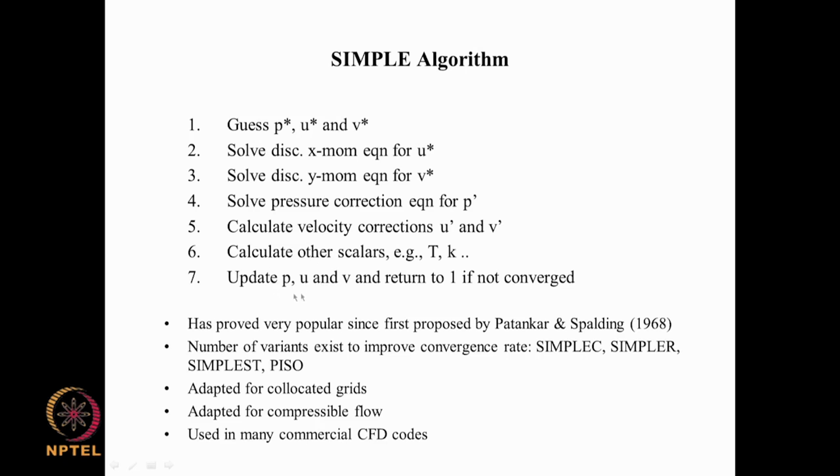So now we have updated pressure and velocity components, and these updates are used to now go back to step 2 and solve again the x momentum equation and then the y momentum equation and the pressure correction equation. We do this iteratively.